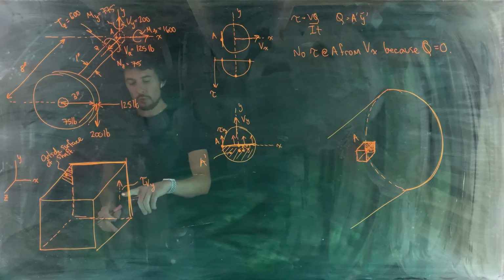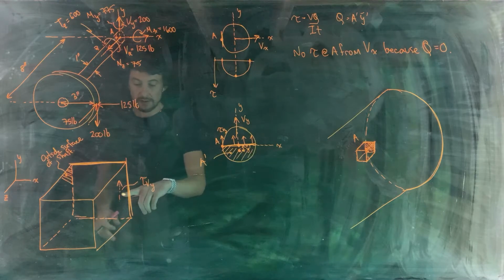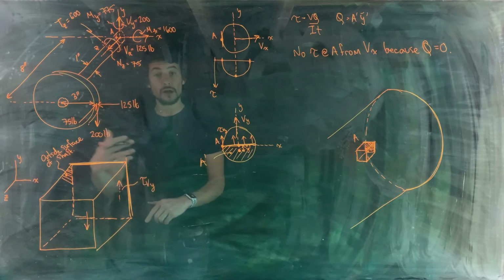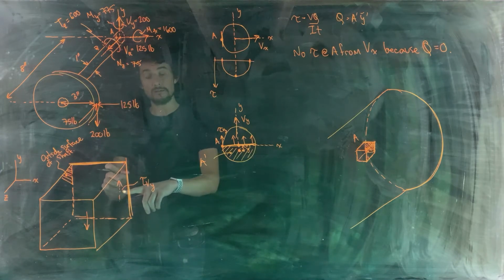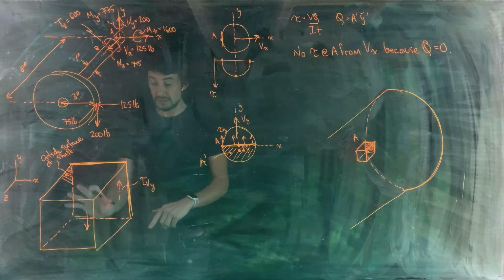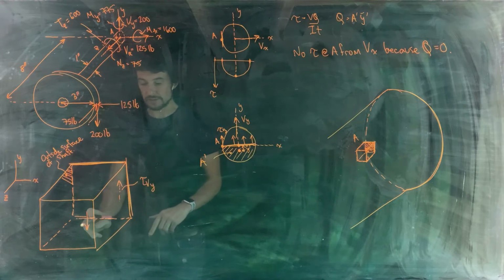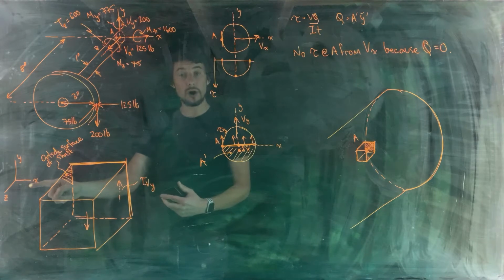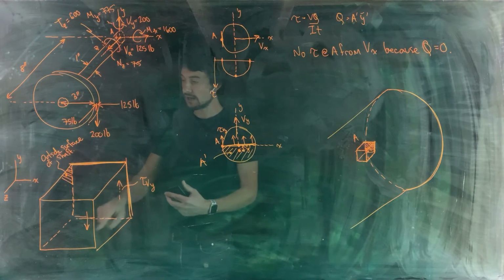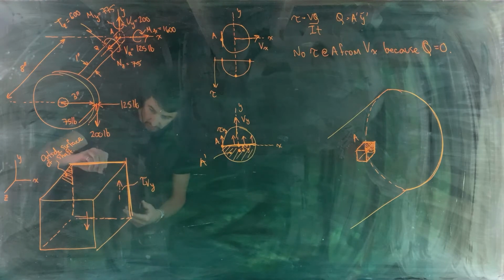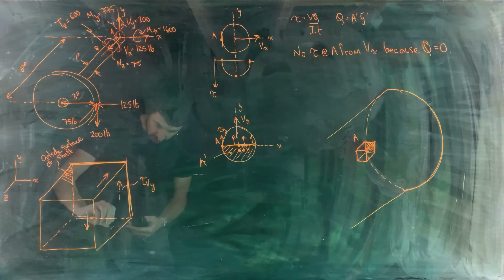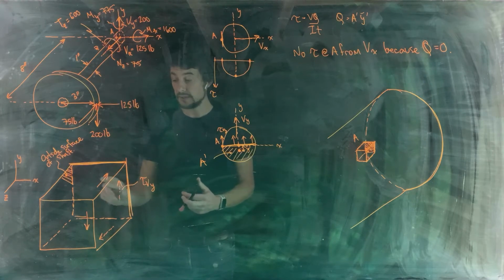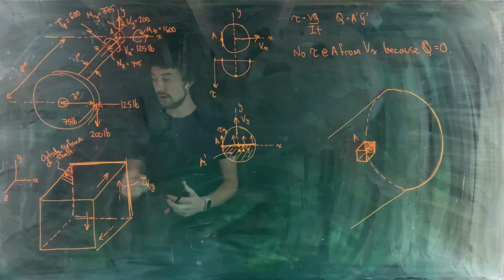Okay. Now, when we put one shear stress on, we need to have an equal and opposite shear stress on the front face, like this, because we know that a stress multiplied by the area it's acting over will create a force, and we need to have that force balanced if the piece of material is in static equilibrium. So if we've got tau Vy there, we need to have equal and opposite there. And then that creates a force couple which wants to rotate this element about the x-axis. So we need to have an equal and opposite pair of stresses on the top and bottom, creating a counteracting moment around the x-axis. So we also need to have a shear stress on the top face there and on the bottom face there. Okay. So whenever you place one shear stress on an element, you need to have 3 other shear stresses. So the shear stresses always need to occur in sets of 4.